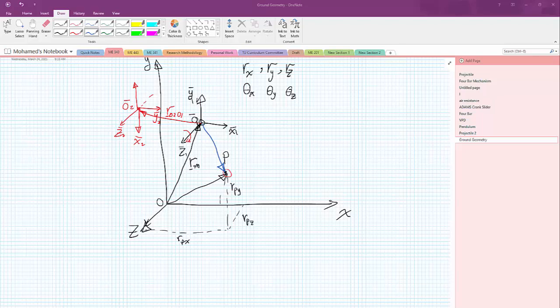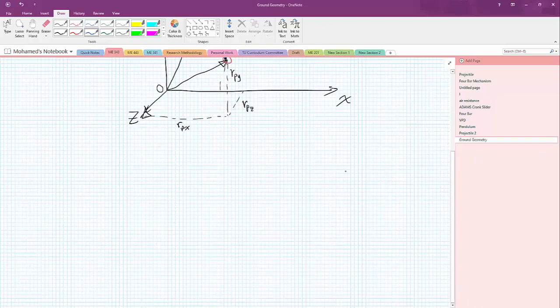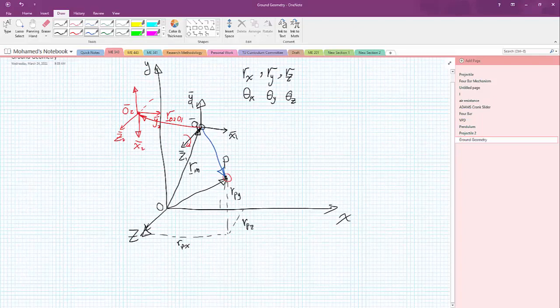Those two important parameters we can use to define the sphere. Once we define those parameters, the sphere can be created. So how do we define the center of the sphere? We can define the center of the sphere by a marker. So I can say the center is located at this marker, the origin of this marker, or at this point.